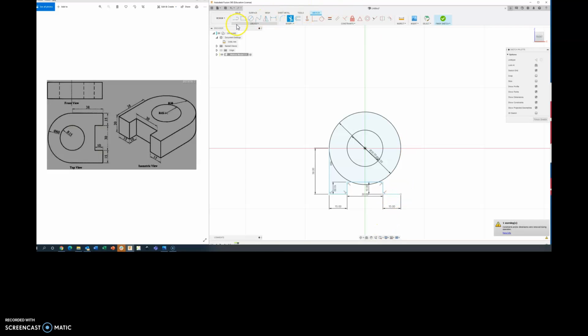All right, so let's try again. Choosing a line, and I'm going to draw it up here. And okay, that's what I need. I need to specify my next actual point on the circle. So typing 38 should work now that I've touched the edge of the circle. So let's try that.